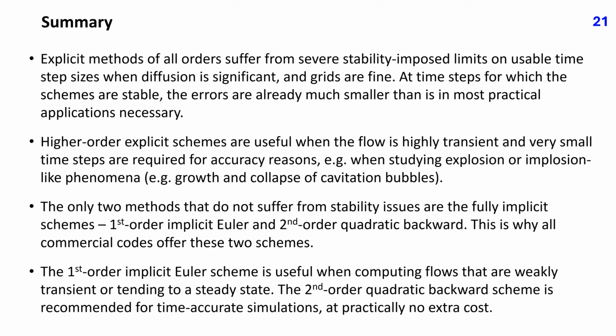Higher order explicit schemes are useful when the flow is highly transient and very small time steps are required for accuracy reasons. For example, when studying explosion or implosion-like phenomena, for example, growth and collapse of cavitation bubbles.